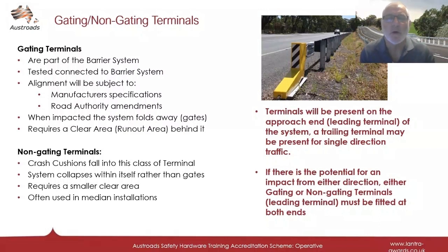Terminals will be present on the approach end, the leading terminal of the system. A trailing terminal at the end may be present for single direction traffic. If there is the potential for an impact from either direction, either gating or non-gating leading terminals must be fitted to both ends.